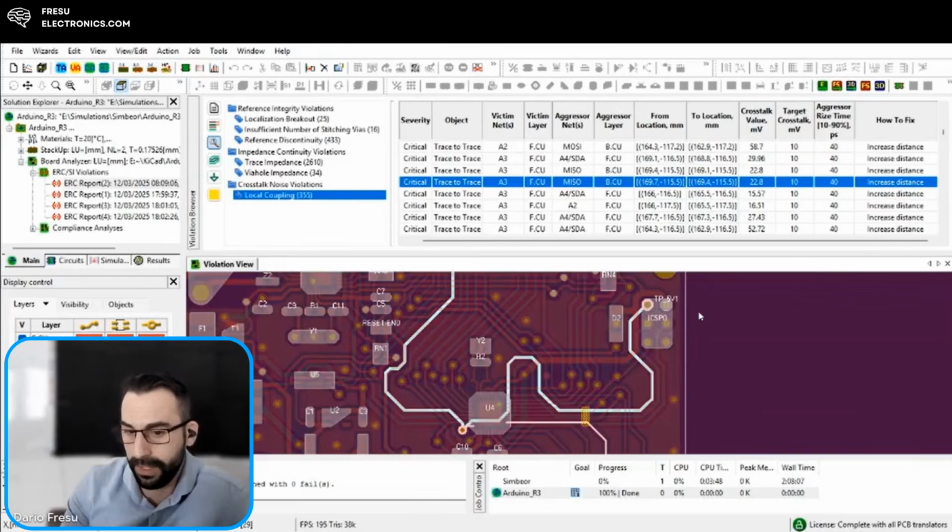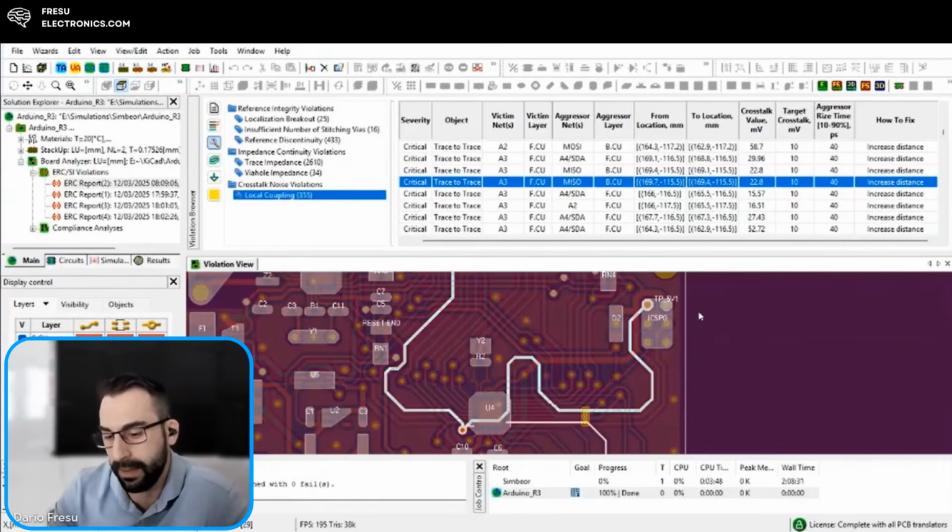But from the EMI point of view, so from a basic EMI point of view, these three things is all you need to begin with. So if you know already these three things, you can already cover 90% of the issues, because then the rest becomes more of an issue of how did I place the cables? How did I place the components? So do I have the board partition or not? But these are, I would say, second stage issues. The most important are those. And these are the most common ones. I promise you, if they give you a board that is failing for EMC test, check these three things.